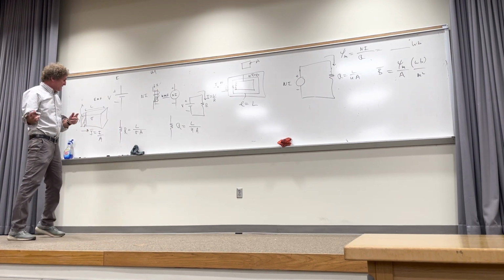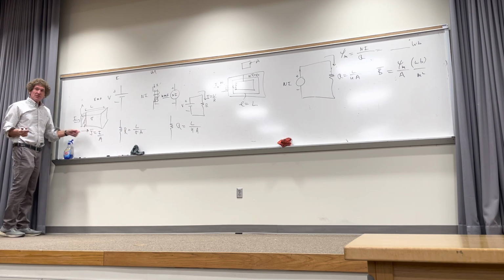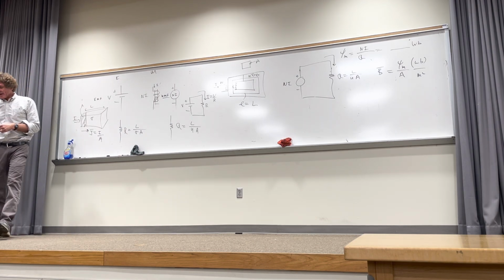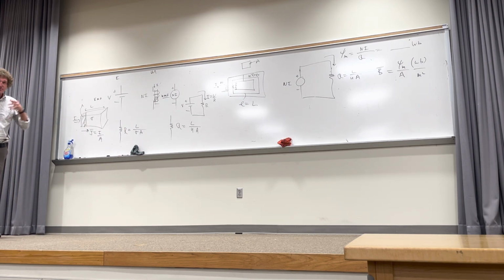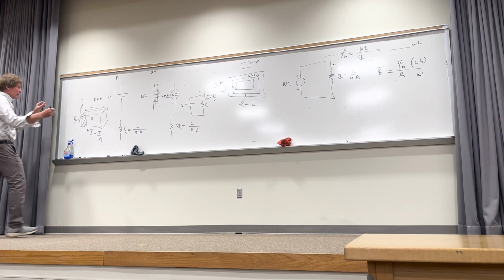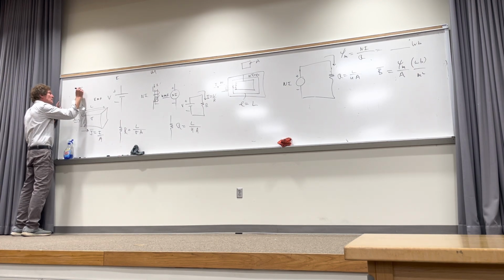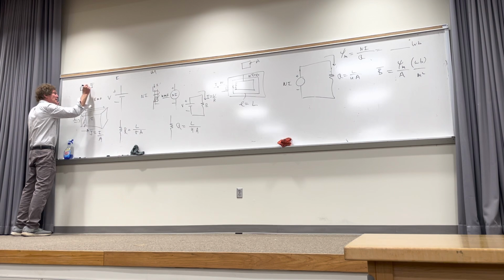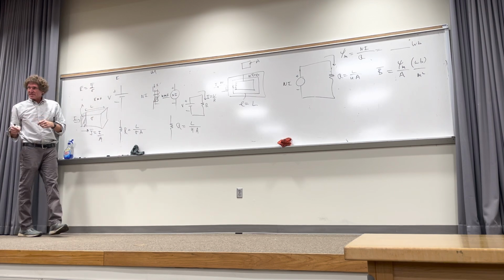Now, next, let's go back here for a second. If you have J, do you remember when you did these calculations of resistance? You would assume current, right? Then you would get J, assume it uniformly distributed. After you got J, what was the next thing if we're going to get resistance? E. Do y'all remember that? We would say E was equal to J over sigma. Y'all remember doing that stuff, right?